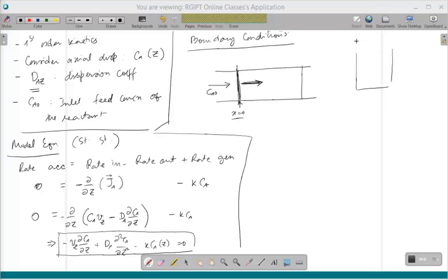It's something like, if you recall the CSTR, when you have a feed that is entering with C_A0, as soon as it enters the CSTR, due to homogenization, the solute is immediately spread over the entire region. That leads to a very important effect, which is that the C_A here is not equal to C_A0. The concentration inside the reactor is not the same as the concentration of the feed. Something similar happens here.